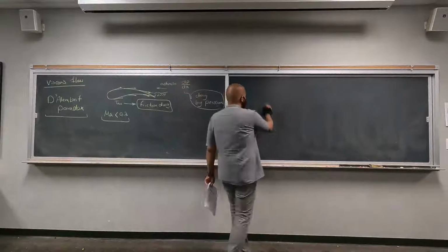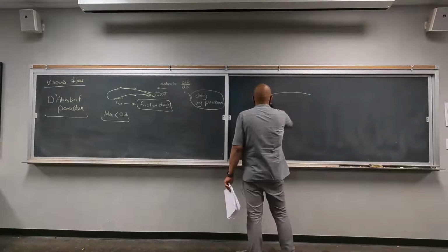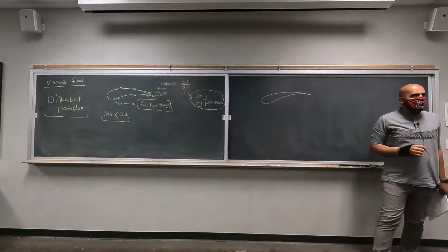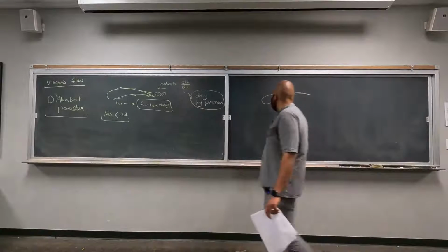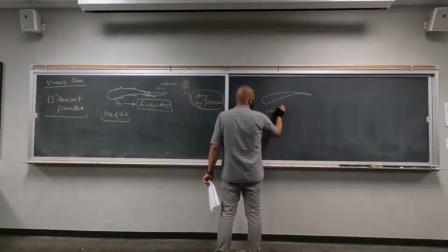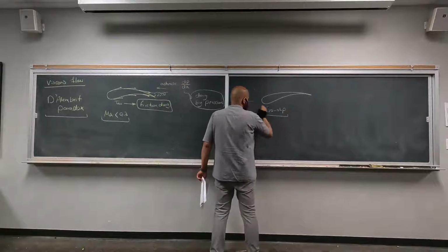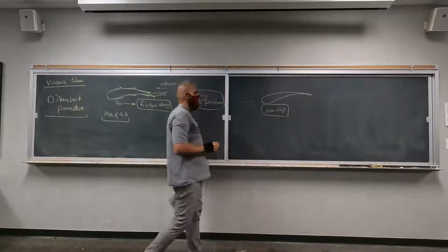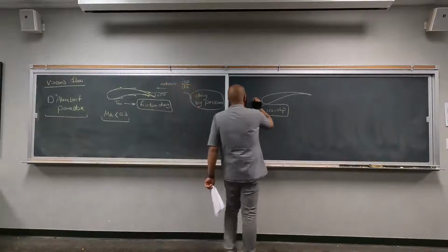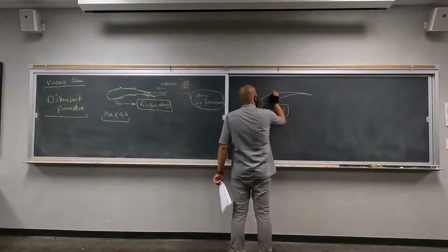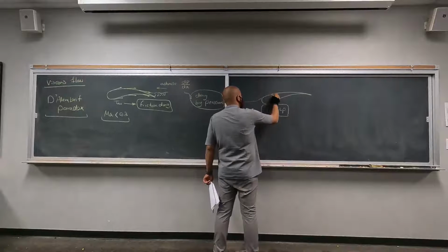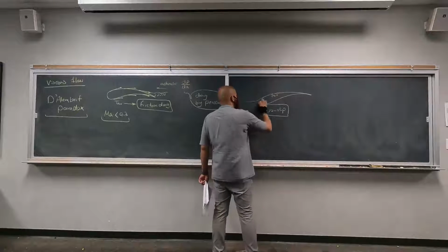Boundary layer formation, right? This is also something that you had in your exam. The idea is the first layer, if we have no slip conditions, which means no layer of fluid can slip on the wall, the first layer will lose all of its momentum to the wall, which means that the velocity here is going to be 0, right?